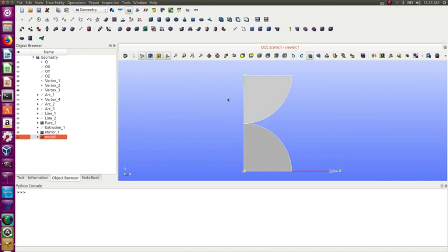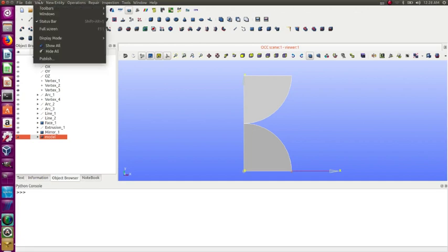So what I will do is block this edge here. I will block the displacement in x on this edge. I will apply a displacement of 2 to this edge here, and a displacement of -2 to this other edge here. So the two shapes here will have a contact at this point, and we will see the contact pressure here.